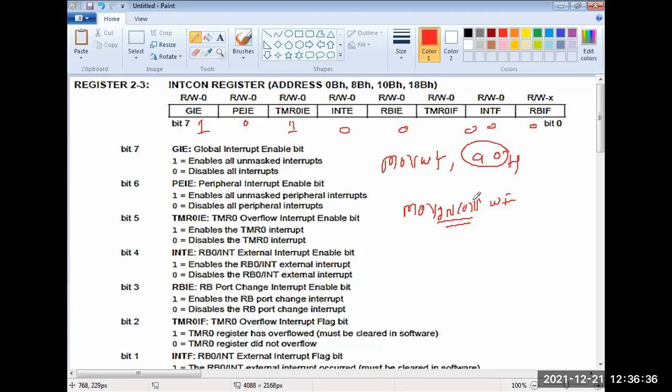So what is the meaning of this? The INTCON will control and set the timer 0. And we have the timer 0 register, TMR0. I'm loading it with the value F8. Once I start the timer by setting TMR0, the timer starts incrementing the value, and when it reaches the limit, rollover occurs, that means overflow occurs and the flag will be set here. I can check that value.